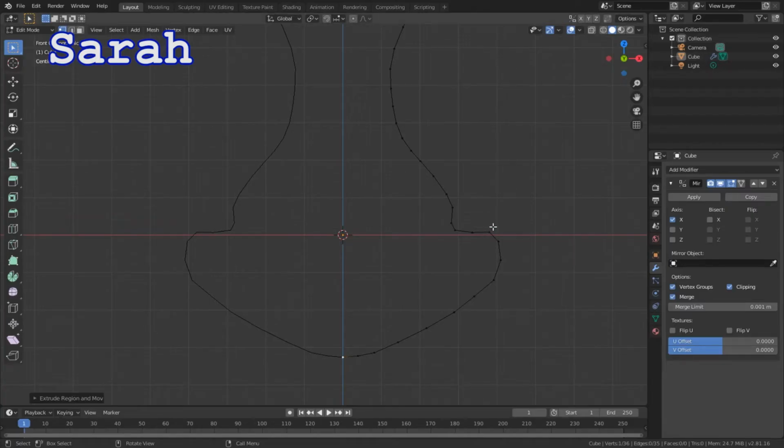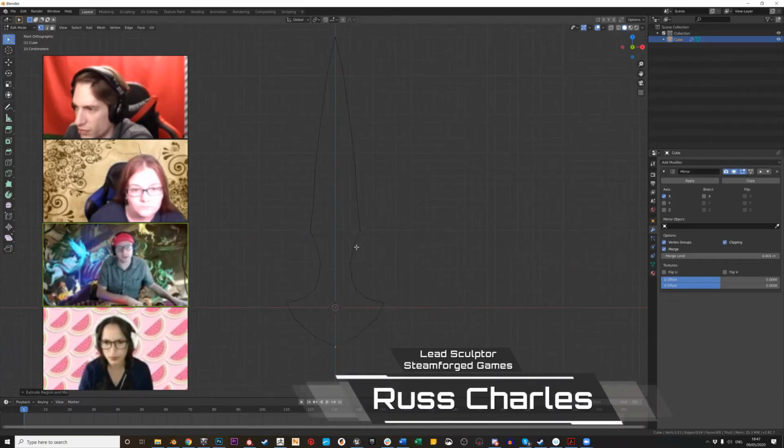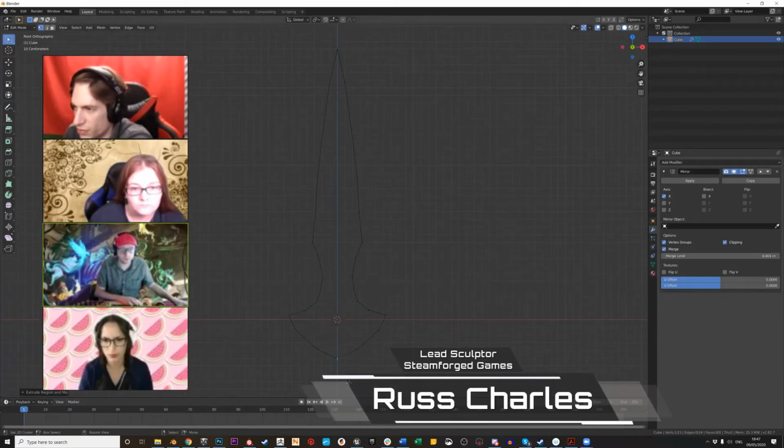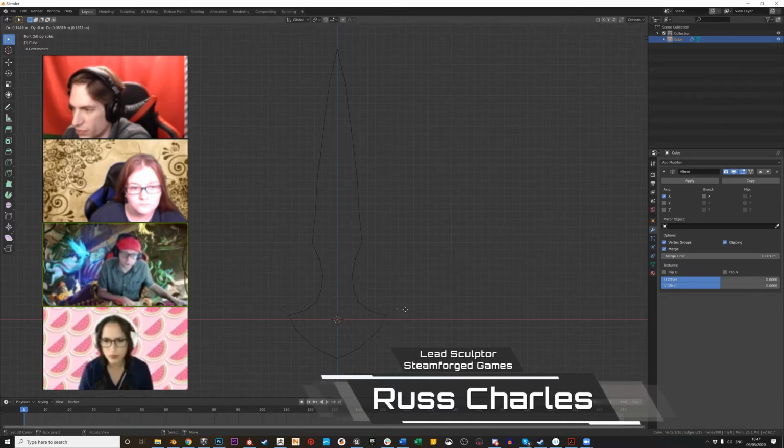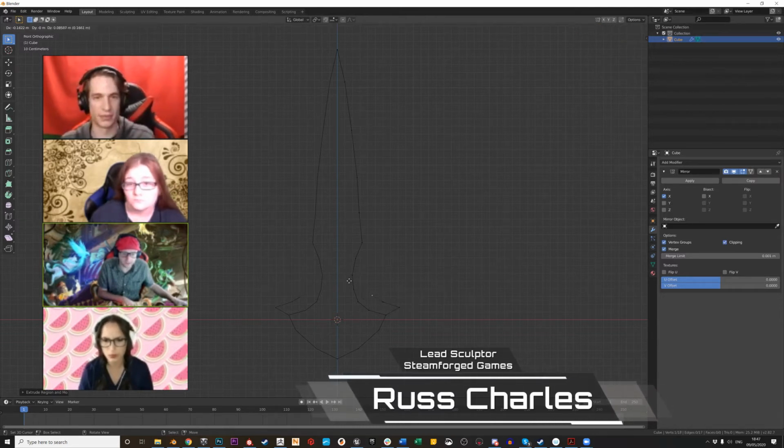Now what we're going to do, or again I'll demonstrate it on my screen, is we're going to put a blade edge on this sword. You can start this more or less anywhere that isn't the center, but I'm going to start on this corner and extrude off it. I want to mimic the shape and the number of vertices I already have.